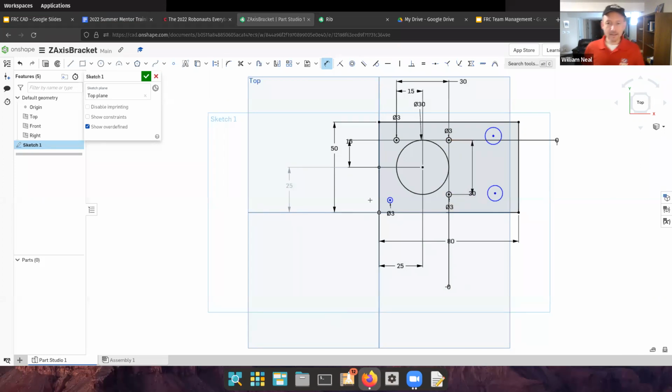There we are. One more point to constrain. I'll make the vertical distance between these 2 points 0. Trying this out here, that's 0 there, and an enter. Didn't catch, so that's okay. Try that one more time. There we are. And you see that distance there is a little bit too much, but if I make this a distance of 30 only, now I should have these 4 holes centered about this central hole here.